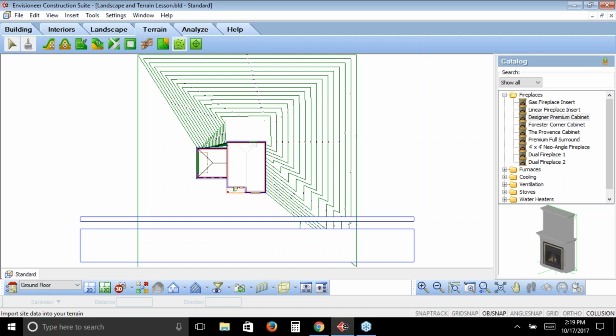If you're using, again, our Pro Architect software, you have these tools right here: hills and valleys, berms and trenches, plateau, and slope. And just as I showed you, they're very effective in being able to show that berm along the entire edge, that plateau at the back of the site itself. But they're just showing those points and then showing it as it would gradually go into a zero terrain, because we had that zenith that we were sliding, or if it was very steep. So that was your only way of actually showing the difference in how it's going to achieve the different levels. Whereas if you had the spot points, you can show exactly where the spot differences are.